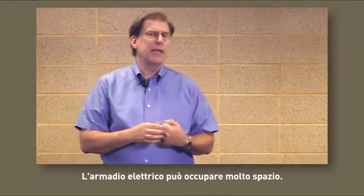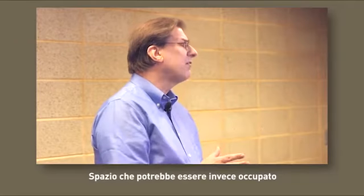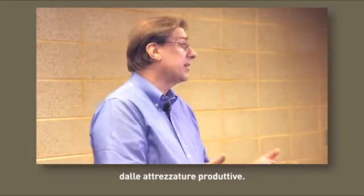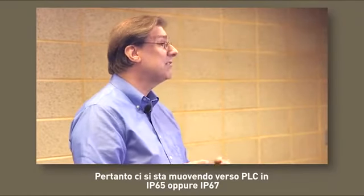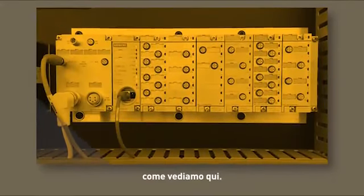So cabinet space takes up a lot of floor space. If I have a lot of floor space taken, that means I can't put production equipment in that place because the cabinet's taking it up. So there's now a shift towards IP65 or IP67 PLCs, such as we have here.